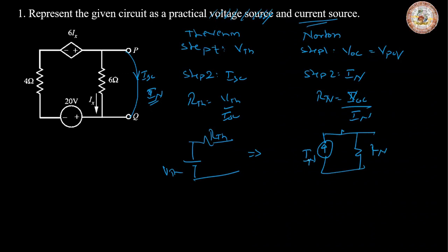However, do not use the term or variable called VTH. You can use any other parameter or variable to find voltage across the load, and then short circuit current. So V by I, you get your RTH. So this is a small comparison to see how these two are different. It is the same as Thevenin theorem. However, only the variables change their names.